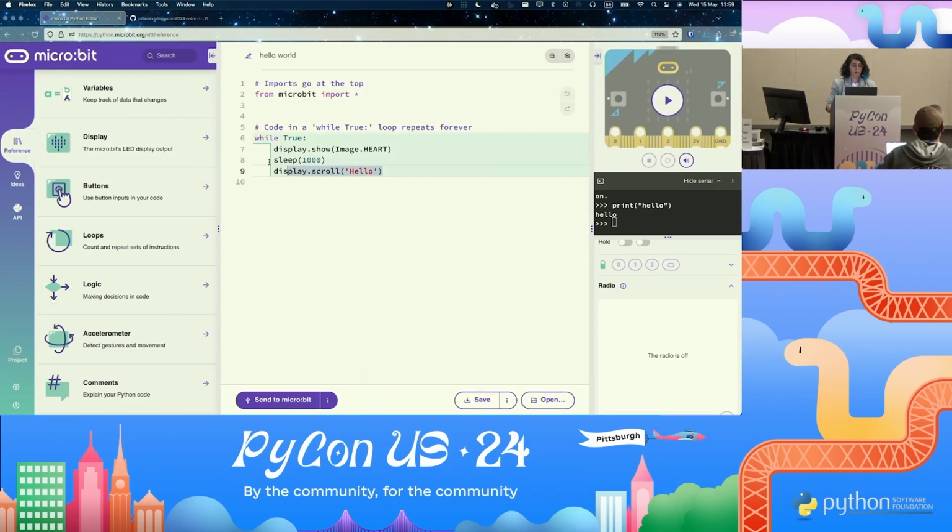So let me see. First of all, we usually have a while true loop, so we can keep the device running for as long as it needs to be. It's a good practice when working with microcontrollers to have all the setup here, and then you have a loop for repeating the function that the microcontroller is going to perform.